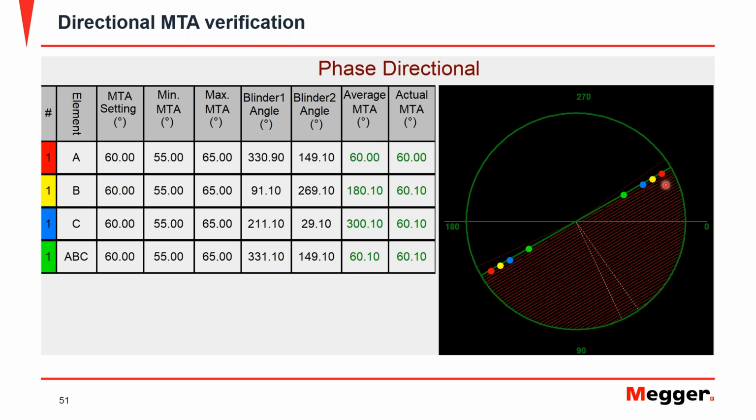One thing that I have seen happen, I'm going to say, to some people testing, is that they try to test this because it is a trip test. They try to test it against the trip signal, and that is fine if you are testing a 50 element. But if you're testing a 51, and you're trying to use your trip signal, then you will see that your trip area goes into the characteristic.